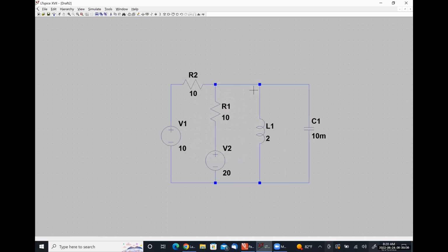All right. So because LTSpice uses nodal analysis, we need to establish a ground. I am in the habit of always choosing the negative polarity terminal of my capacitor voltage as ground, and I'll explain why here in just a second. Another thing I'm going to do is label the positive polarity terminal of my capacitor voltage as VC. So that will be this node up here, okay?